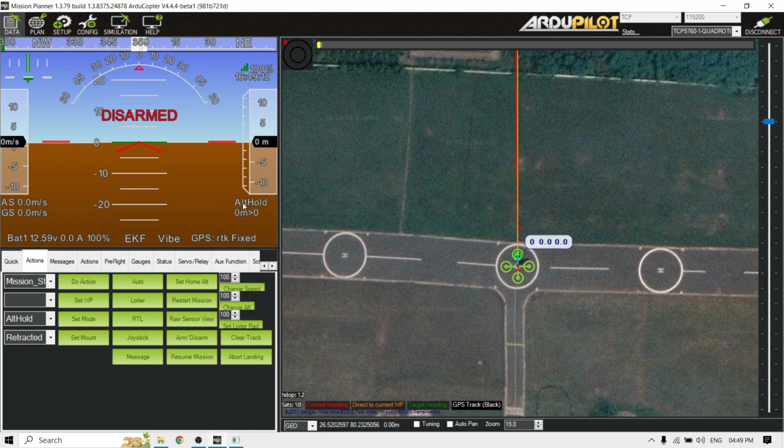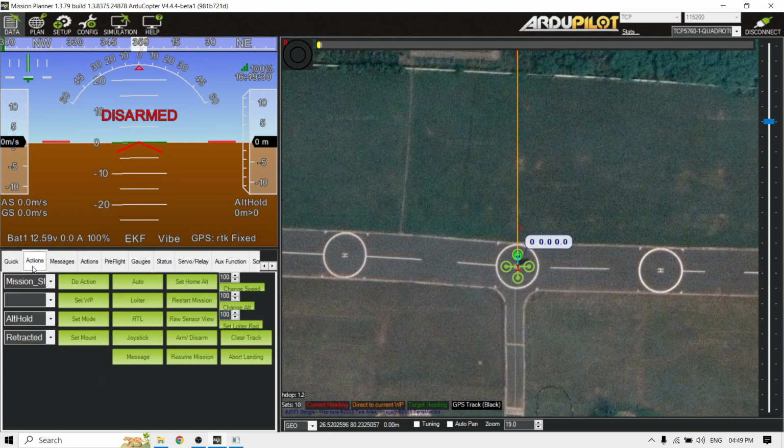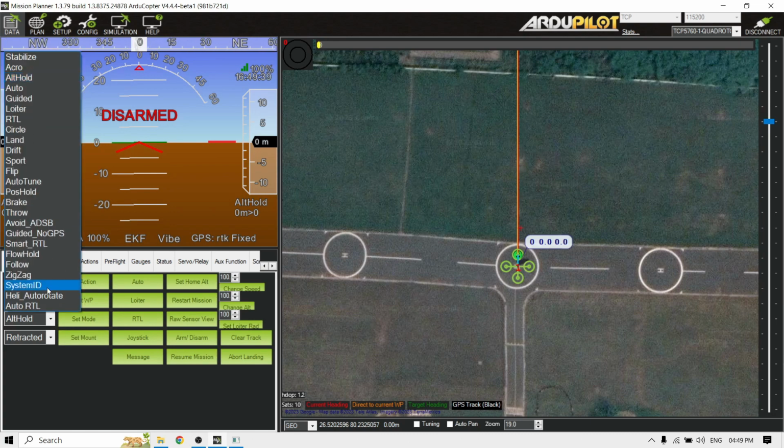See, now it's in altitude hold. We can actually change the altitude now because channel 3 is not exactly 50%, so it would be descending. If it goes above 50%, it will start ascending slowly, or else it will slowly descend. But once you make it 50%, the altitude is locked. You can start playing with front, back, like pitch and roll.